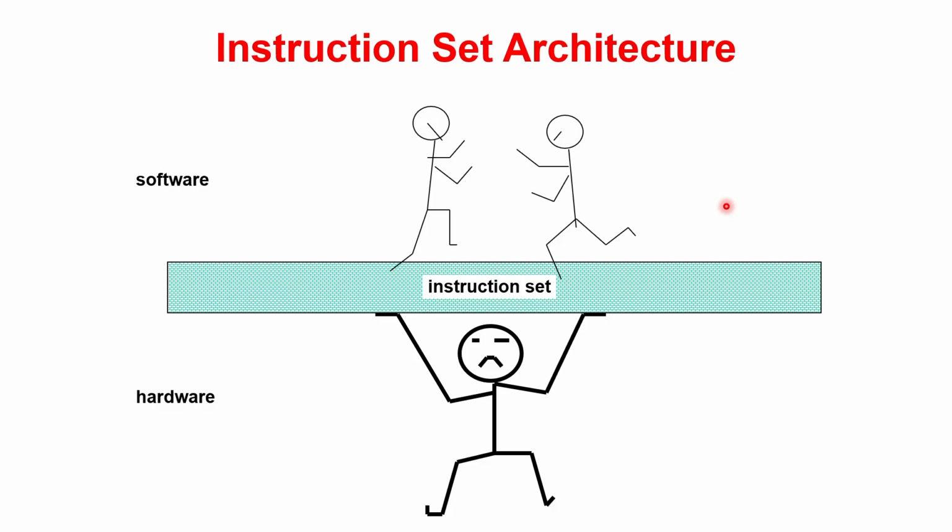And then there is the ISA layer, which is the bridge. The add instruction is part of the ISA. So it defines exactly what add means, what format it has, and how registers are used. On the hardware side, below the ISA line, the control unit decodes this add instruction. It tells the data path to get values from the registers where A and B are stored. The ALU then performs the actual addition, and the result is stored back in the register for C.